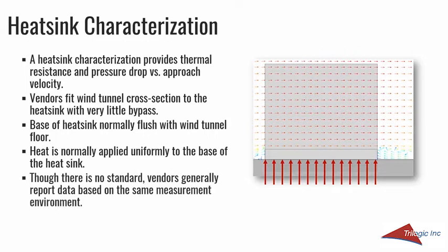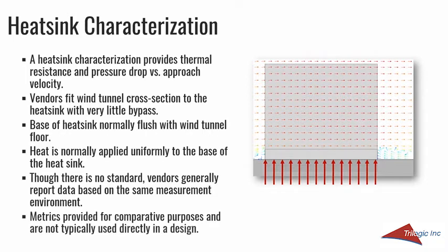I was asked after Heatsink 101, is there any standard? I'm not aware of any standard for heatsink characterization, but vendors generally report data based on the same measurement environment, so they're all very similar that way, I believe. Metrics are provided for comparative purposes and are not typically used directly in a design, because this test environment is going to be different than your system environment. It could help you compare heatsinks from different vendors, and look at the pressure drop versus an applied flow rate and the resultant thermal resistance before you go to the next step.